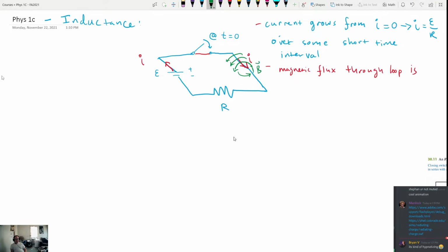Those are the magnetic field lines that will be created there. On this side over here where the current flows this way, the magnetic field lines would be coming up and around like this. Over here where the current's like this, the magnetic field lines are going around like that, just based on the right-hand rule.